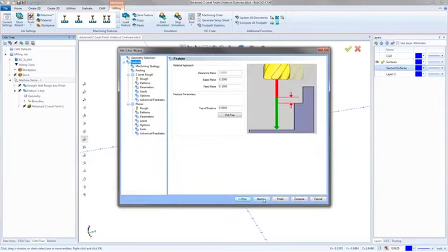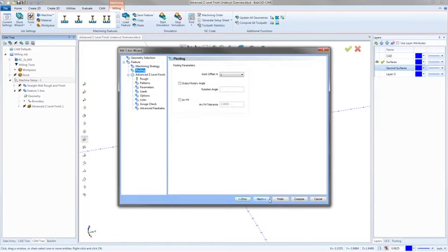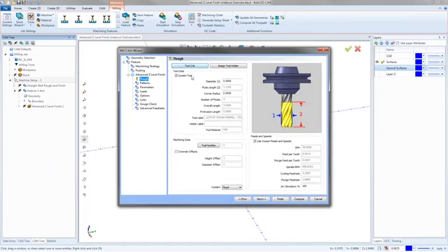Then I go next. So the feature, all this stuff's pretty standard. I'm going to use the advanced Z-level finish. I already have a roughing pass. The advanced rough is doing the straight wall, so it's finishing the straight wall, and it's doing a rough and a finish pass on that portion. But a vertical, a standard end mill cannot cut an undercut. So for this one, I have to go through, turn on the arc fit, and get to the roughing page.